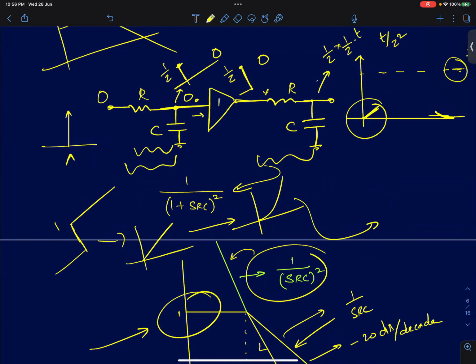You know these two behaviors. So roughly you can say, okay, it's going to start here, and you know the shape of how it's going to start. And you also know how the steady state is going to look. That shape depends upon the input shape, because the DC gain is 1. If the input is flat, the output is also going to be flat. So you know how the function is going to look. Now it can reach this position in different ways. It can reach like this, or it can reach a peak and then settle like this. We don't care about that. Right now I'm focusing on the initial and the steady state responses.